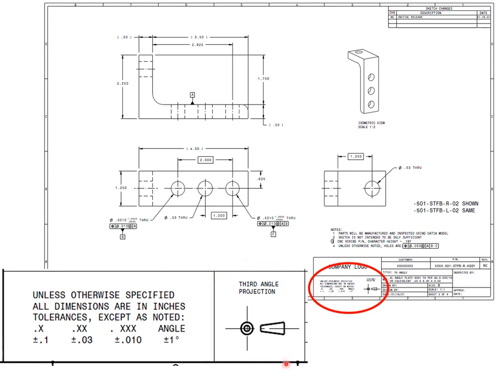Another thing we see in a title block is what projection are you using? Again, in this class, we're only going to stick to third angle projection. If you were looking at a first angle projection, this cone shape would be over on the left side. Again, in this class, we're only going to stick to third angle projection, and this is the symbol for third angle. And again, this is your typical title block and border.